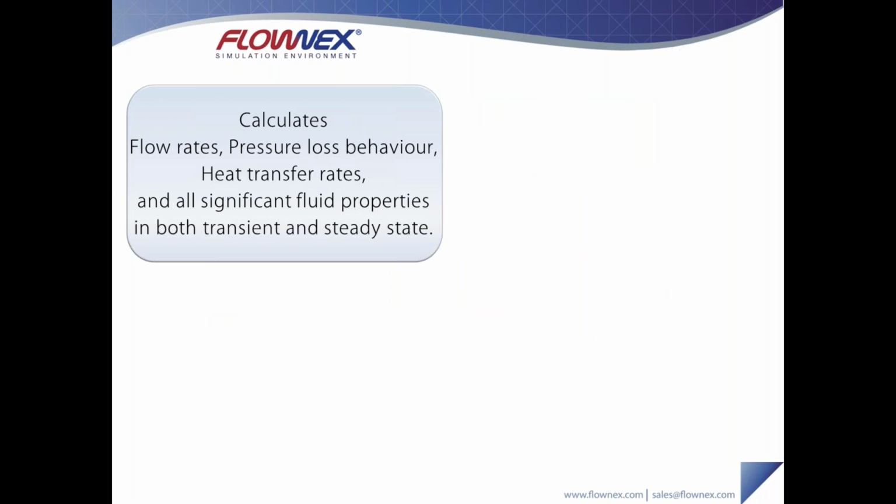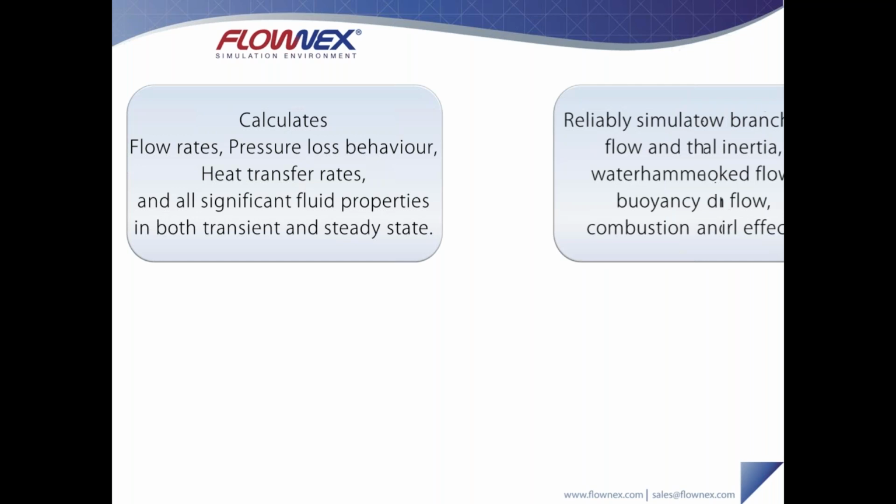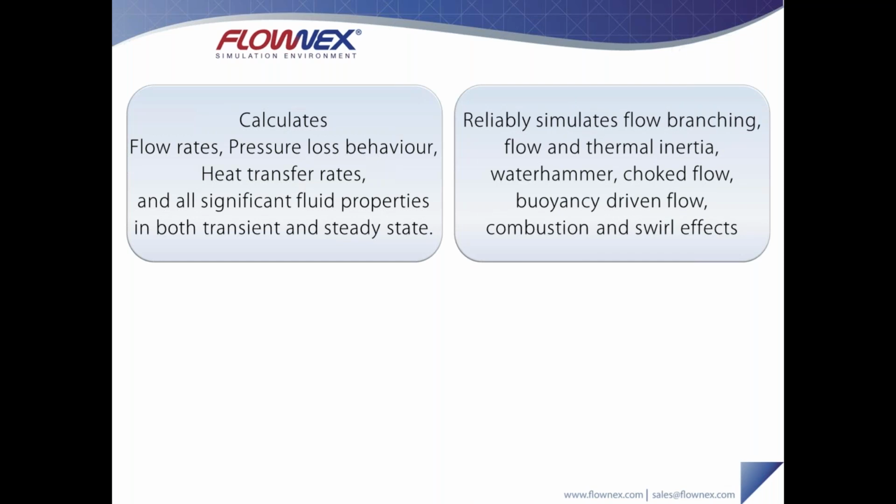Flownex calculates flow rate, pressure loss behavior, heat transfer rate, and all significant fluid properties in both transient and steady state. The significant fluid properties that we are talking about are things like densities, viscosities, Reynolds numbers. So all the information that's required by the engineer in terms of fluid mechanics and heat transfer, that is where Flownex focuses. It reliably simulates flow branching, flow and thermal inertia, water hammer, choked flow, buoyancy-driven flows, and combustion and swirl effects.